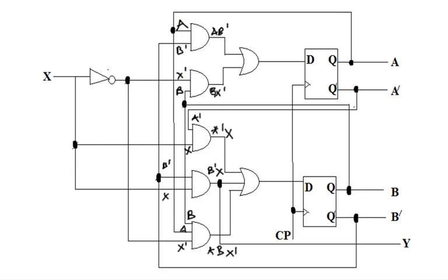That is my first stage gates, and then I look at this one and say, what type of gate is this? This is an AND gate. So I have A and B prime going in, and my output should be AB prime. The same thing with this, BX prime. Same thing with this, A prime X, up to the last one that has three inputs, A, B, and X prime. Now, if I want to get the output of this, all I need to do is to say, okay, this is an OR gate, and for an OR gate, I will add the inputs coming, that is AB prime plus BX prime. And for this one, I have three, that is A prime X plus B prime X, and finally AB X prime. So these are the two inputs to my flip-flops, D and D.